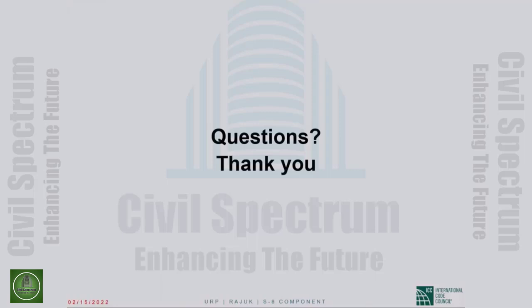So this question is not clear. Is it required to check the serviceability limits for dynamic analysis again when we are satisfied our structure in the ELF method? I do not know. We talked about drift check. If you are doing dynamic analysis, we typically do static analysis only to figure out the static base shear. The drift check is for the dynamic analysis. What other serviceability will we check? At the drift only. Yeah, so drift check we talked about. You have to check the allowable drifts basically.